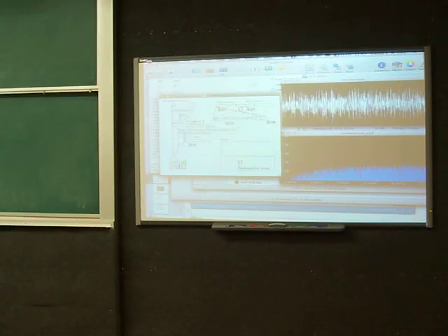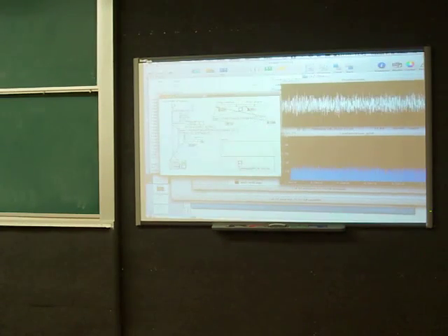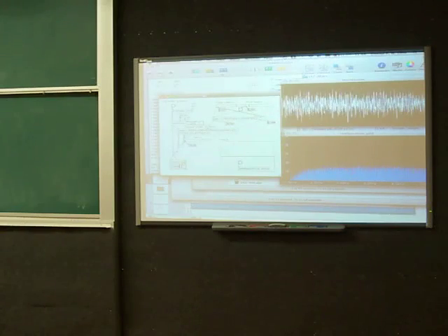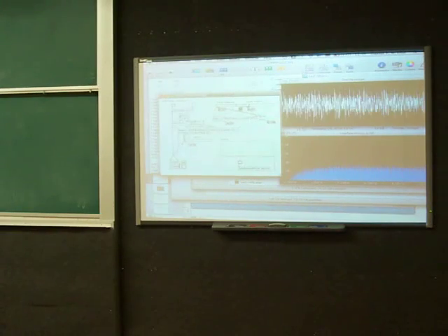Okay, there we go. So now when I have the gain at 0 here, then the audio is just coming straight through and going straight out. But here's my second order all pass section with my pole, radius, and angle. So if I have a lower angle here, that's a lower frequency thing. So now if I have a positive gain, that's actually a notch filter. If I have a negative gain, that's a bandpass filter. Let's see if we can see that.